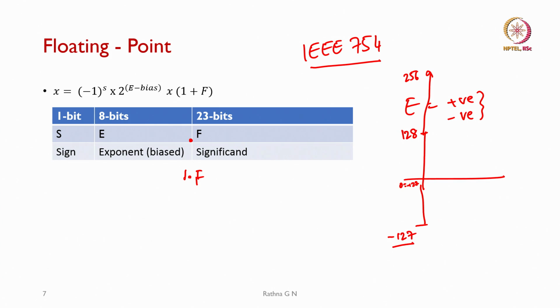We went on to discuss some of the problems, both in fixed point multiplication and addition, and floating point addition and multiplication, and how we have considered them. In most architectures, as we know, multiplication is going to multiply the fractional bits in floating point and add the exponents to get the result.